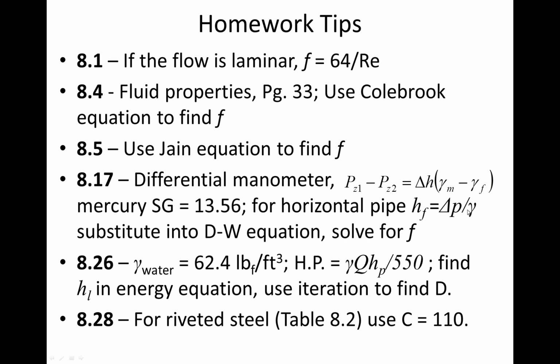As long as you divide by the unit weight of the fluid flowing through the pipe, you can get the h sub f from that. And then in the Darcy-Weisbach equation, of course, h sub f is the whole point of the Darcy-Weisbach equation. So if you put that known value for h sub f into the Darcy-Weisbach equation, you can back calculate for the f value that's making that entire problem true. That's the essence of problem 8.17.